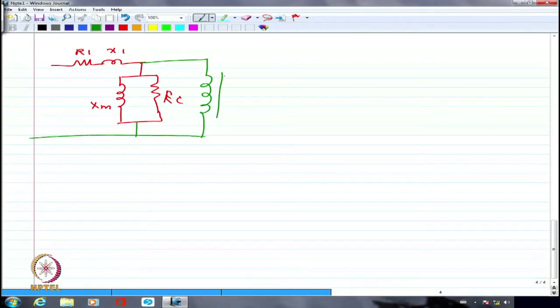Now I am going to have the iron core as well. This is now S times E2. It's not E2 anymore. Right? Because it is in rotating condition. I am not drawing this for stationary condition. This is going to be S times E2. I will have R2. Agreed.